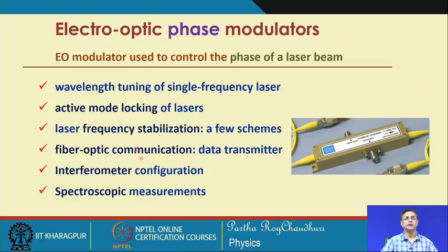factors. When the electro-optic modulator is used as a phase modulator, it controls the phase of the laser beam, the phase of the electromagnetic wave. That has direct application in wavelength tuning of single frequency lasers, active mode locking of the laser beam, and laser frequency stabilization. There are a number of schemes to do that.